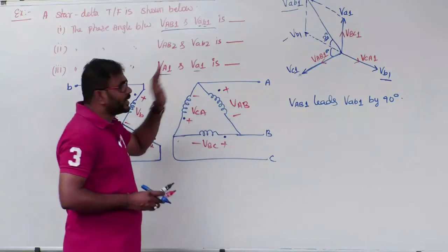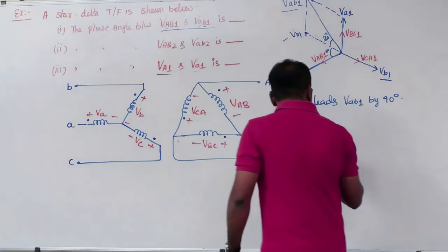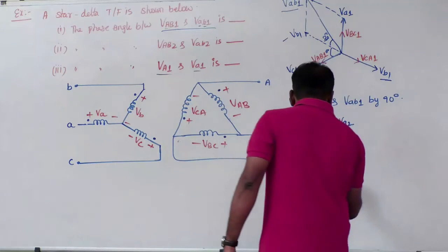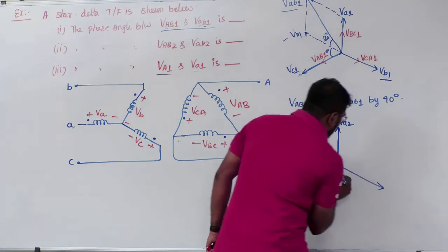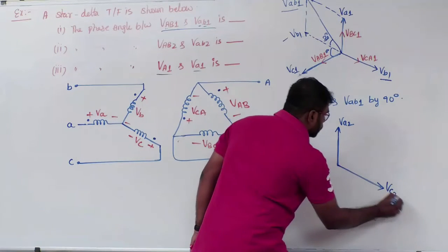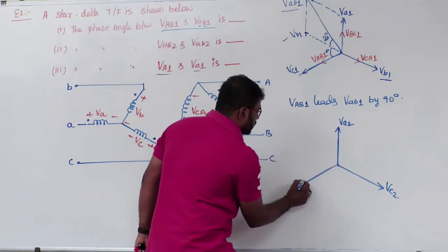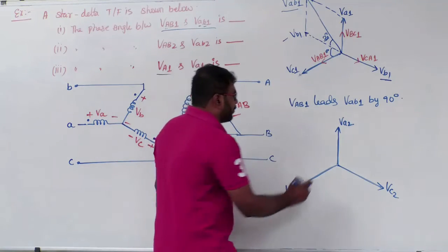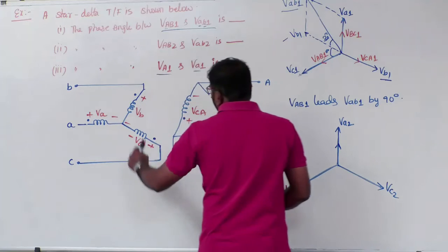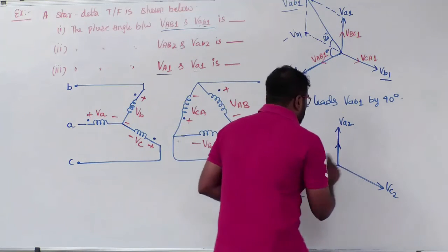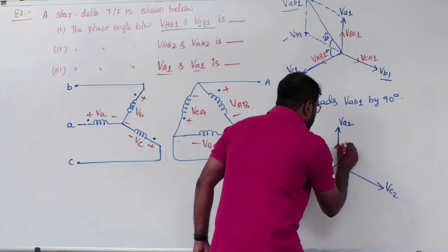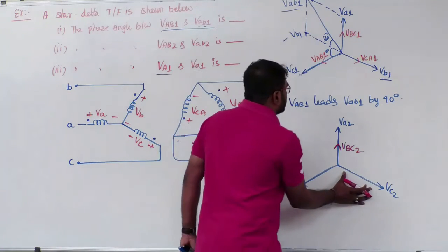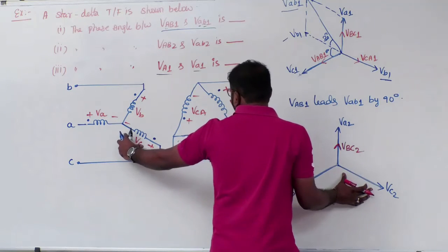Now we will write for the negative sequence. So for the negative sequence, have a look. This I can write as VA2. Now what about this? After VA2, what next? VC2 and then this is VB2. ACB, negative sequence, no? Right. VA is in phase with what? Again, A and BC are in phase, so nothing wrong to write this is VBC2.